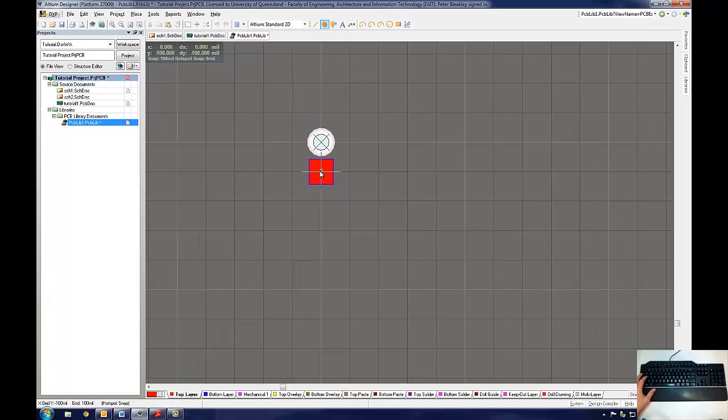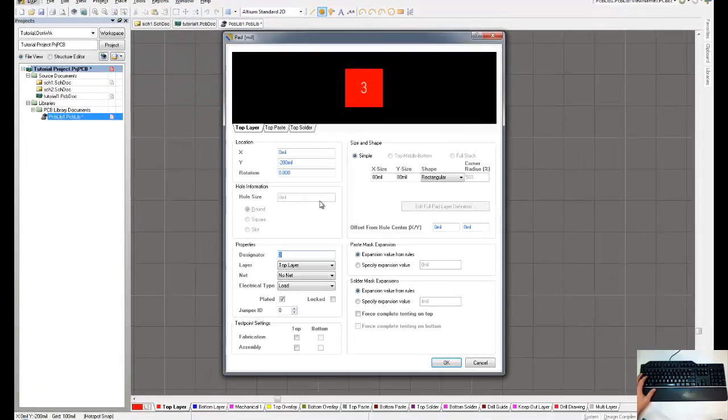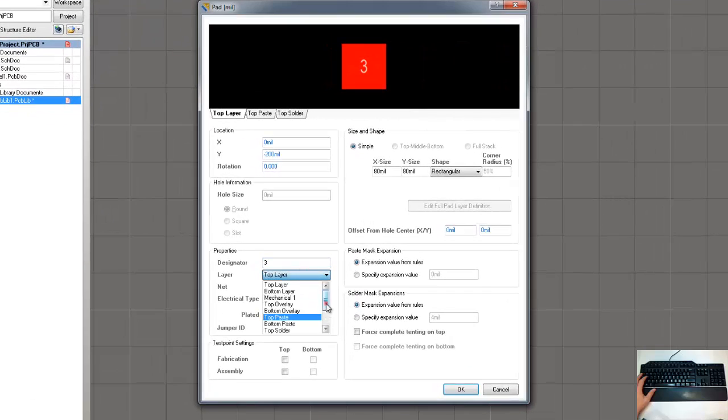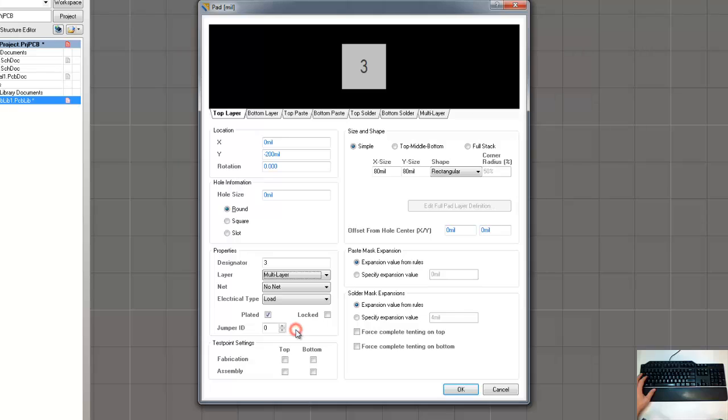The pad attached to the mouse cursor will have been updated to reflect the changes implemented by the user. If the grid of the document has been set up correctly, the user will simply be able to click consecutive points on the grid to place pads precisely. Every time the user places a pad, the next pad will automatically increment its value to the next number.